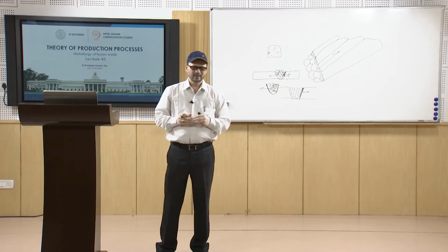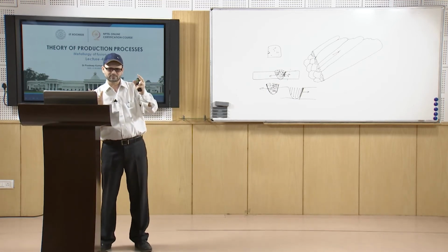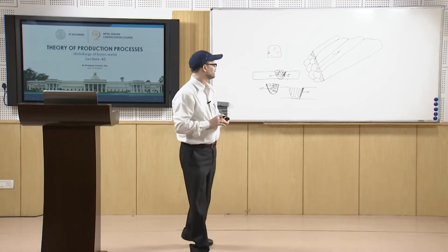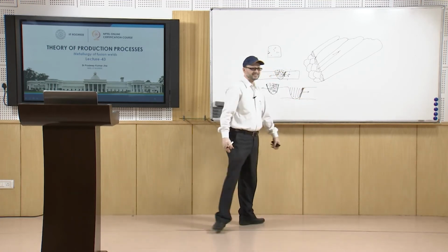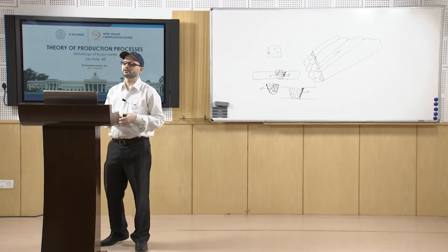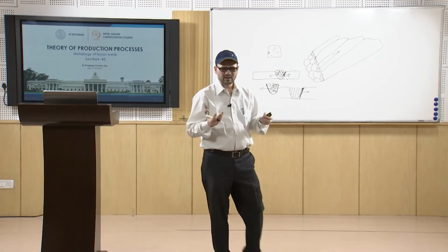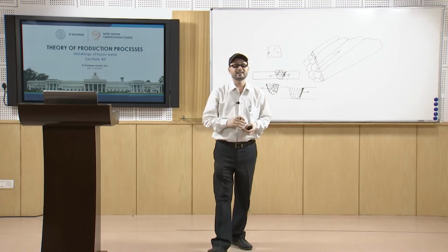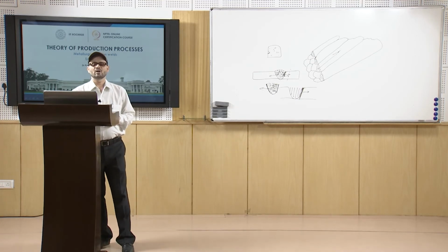So, you do not see a visible fusion zone, because the melting takes place over a range of temperature. There will be partial melting in this zone itself, and this is not considered to be a desirable situation. Whichever alloys behave similarly, that is, materials with large freezing ranges, are said to be very difficult to weld. So, they are difficult to fusion weld.